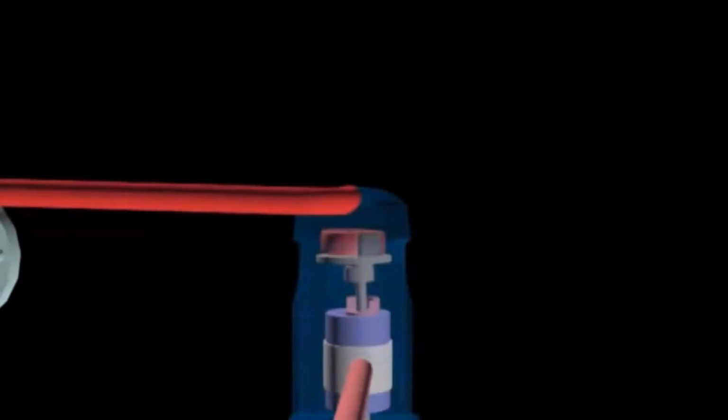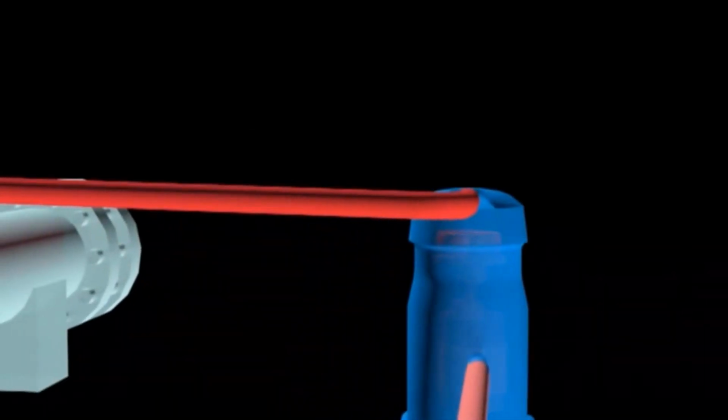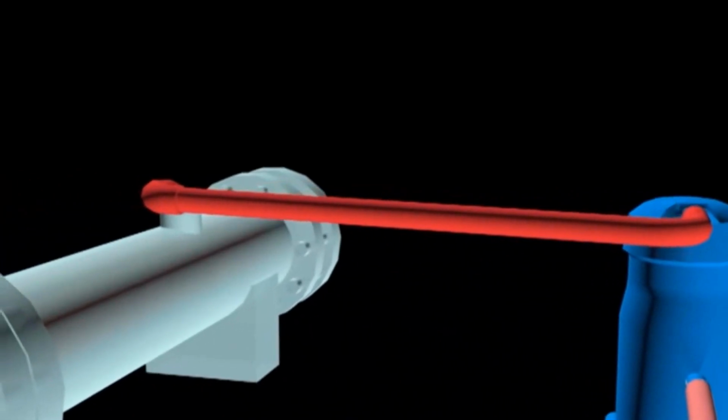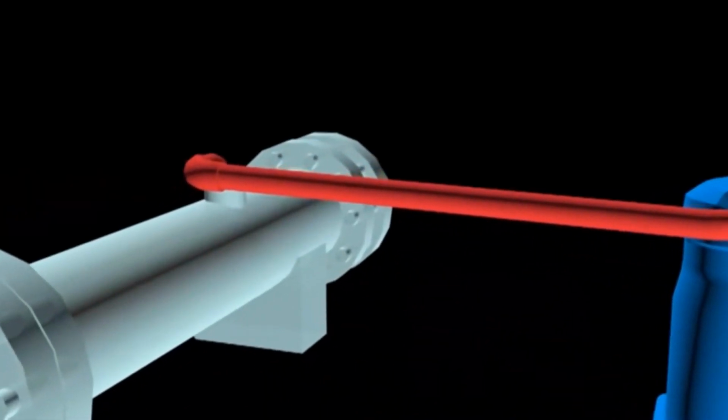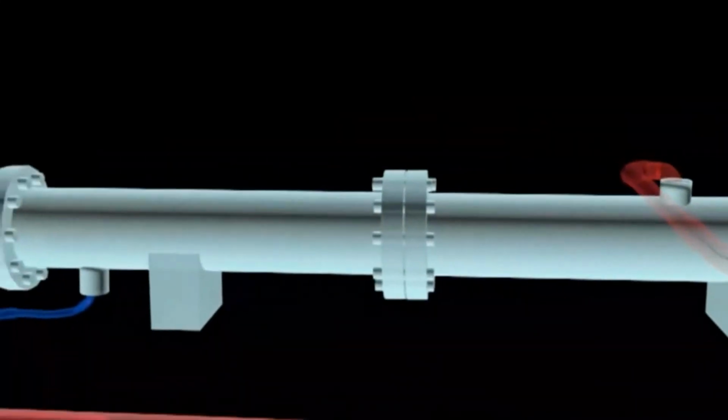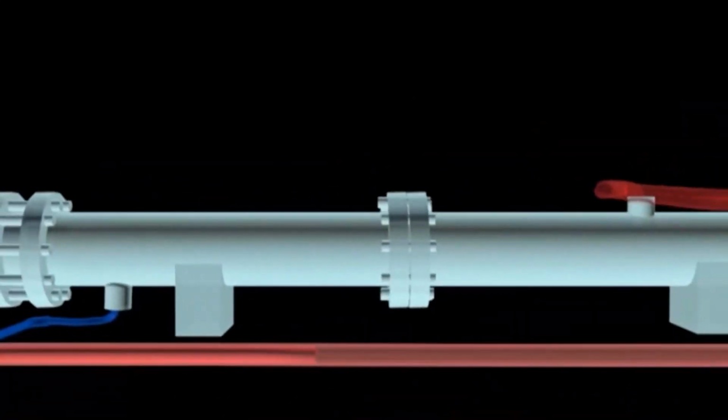Condenser. The refrigerant in high pressure gas enters the condenser at a temperature higher than the temperature of the condenser water. In the condenser, the heat will be eliminated to the condenser water from the cooling tower through the process of convection and conduction. After the heat is removed, the refrigerant in high pressure gas is condensed into a high pressure liquid when it goes out of the condenser.